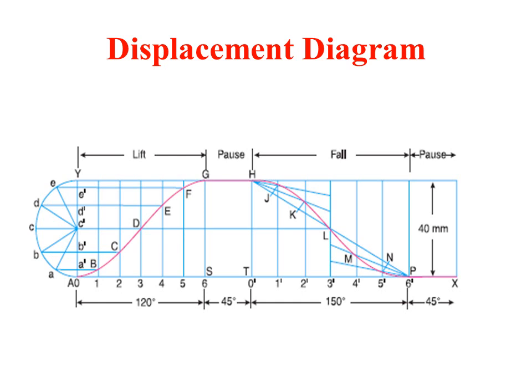Again when you draw the line, it intersects 2 dash at K. Again if you draw H to 3 dash, it again intersects 3 dash at L. So again join this with a smooth curve. So this completes the displacement diagram during outstroke following uniform acceleration and deceleration or retardation. Next we have the dwell, just draw a straight line.